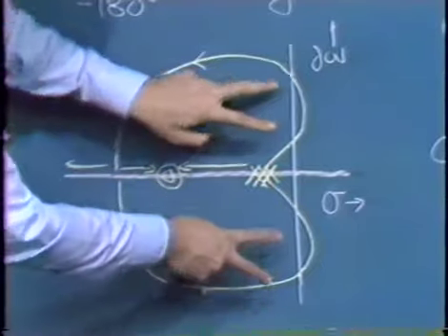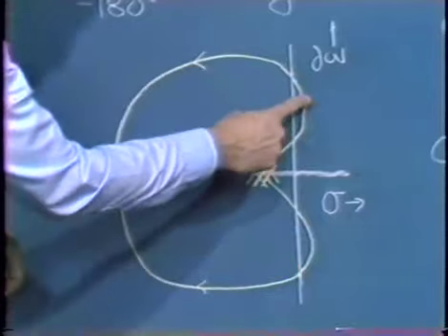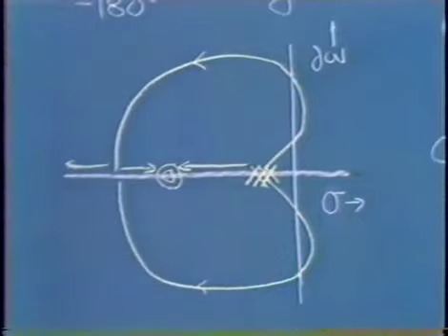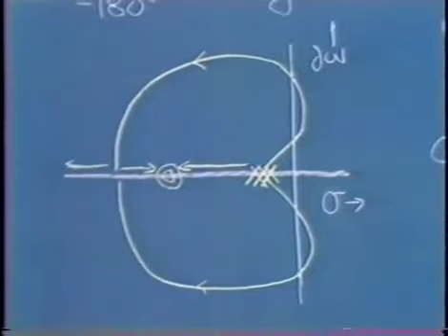There'd be an intermediate range of A naught F naught product where 2 of the system closed loop poles lay in the right half of the S-plane. Consequently, the system is unstable. And then for still higher values of the A naught F naught product, once again, all 3 branches lie in the left half of the S-plane.